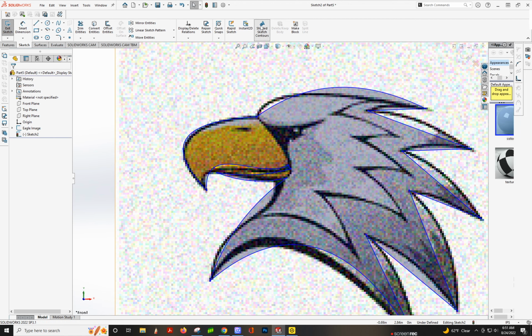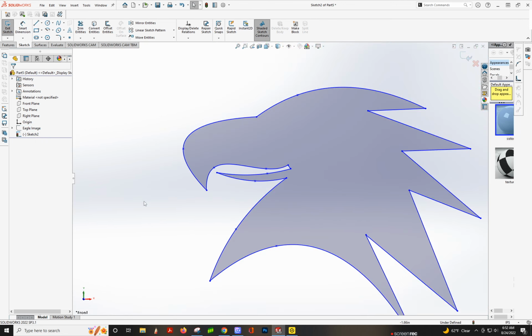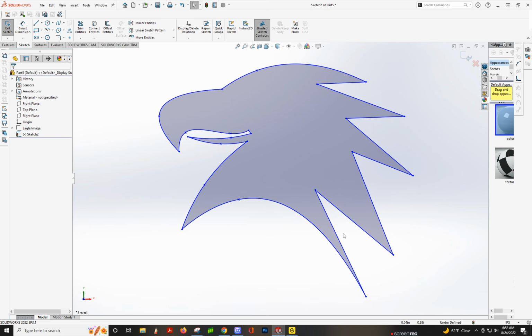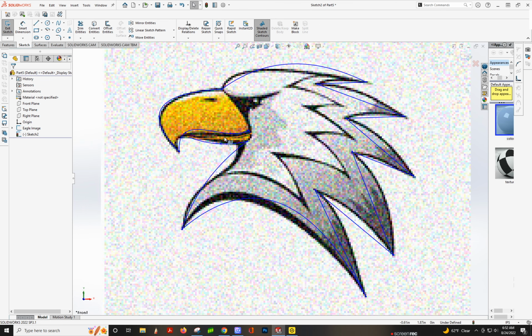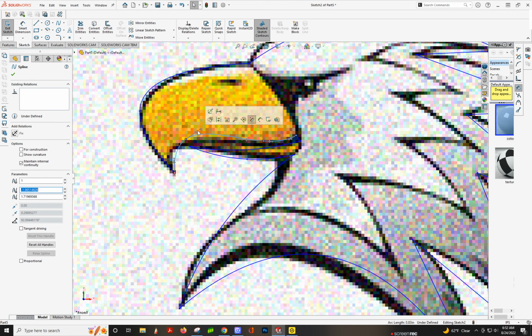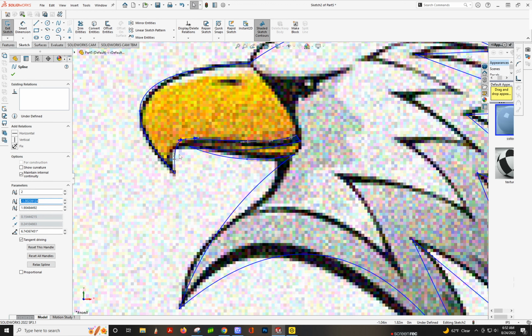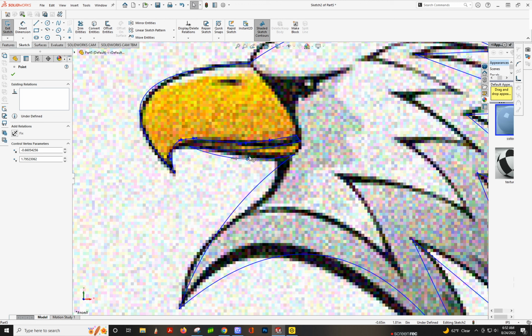So now I've got sketch contours on. Also learned from Solid Professor. Had not known about that for 20 years. So we can see it's closed, and that looks good enough for this phase, which is tidying up. So we're gonna make sure nothing is overlapped on these sketches, because then your extrude won't work and you'll be wondering what's going on. So, all right.